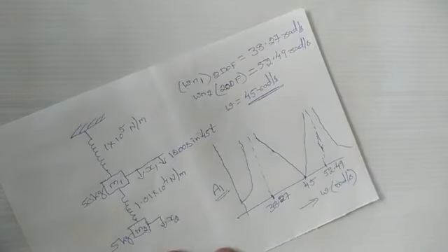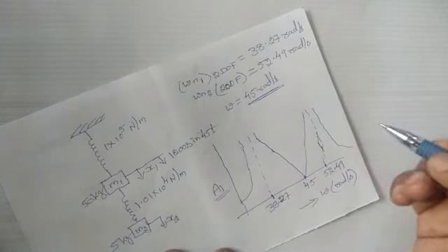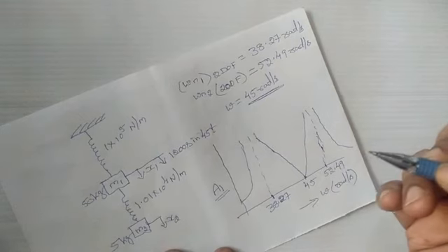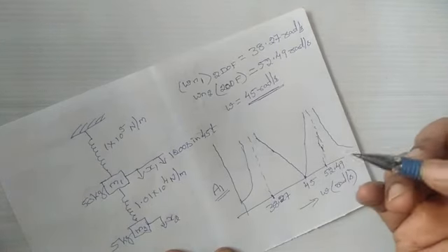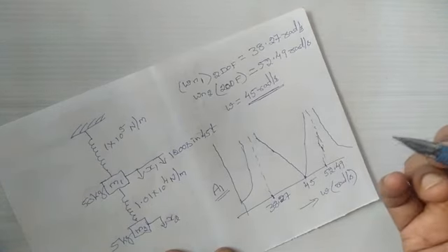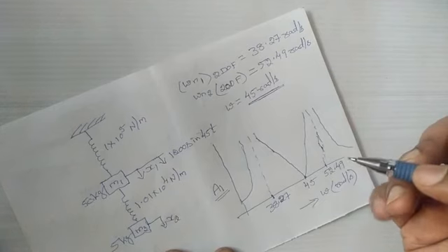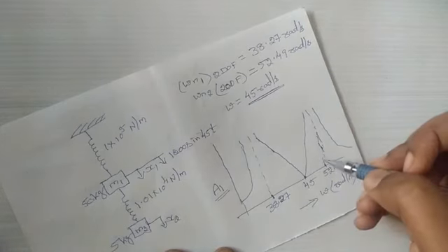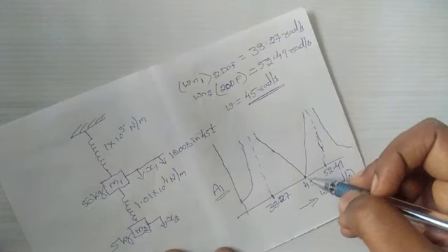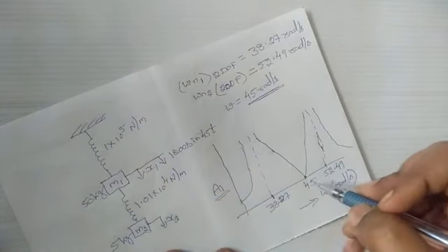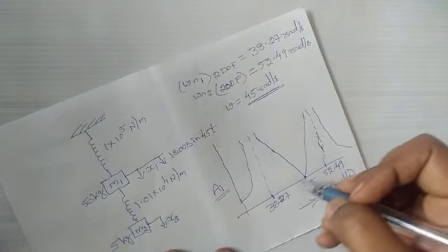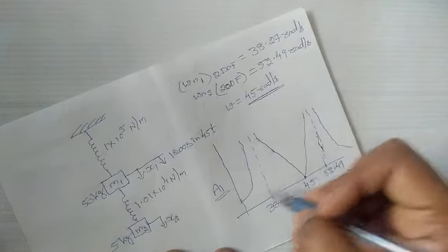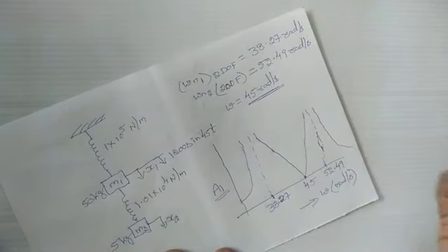So what do we understand by this? We understand that the vibration absorber, which is also called the dynamic vibration absorber or the tuned mass damper, these are the different names by which it is called. So what it means is, this absorber is tuned for this particular frequency. So any deviation is going to increase the amplitude of vibration.